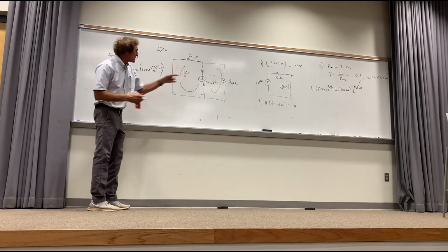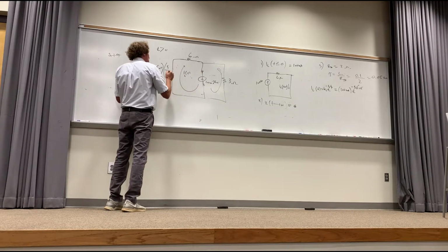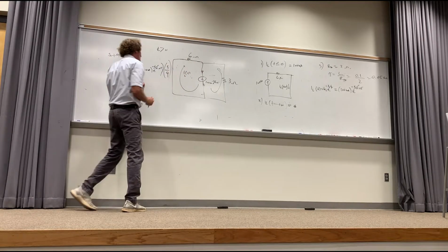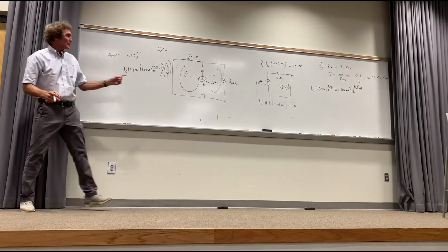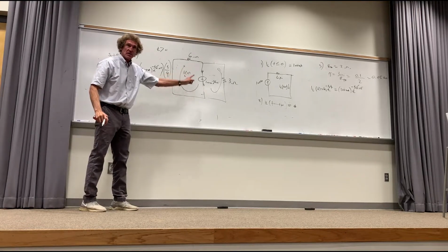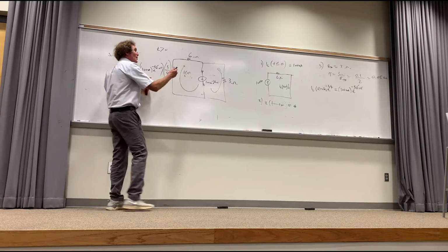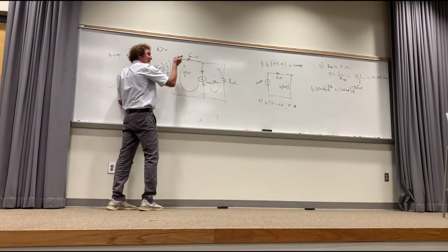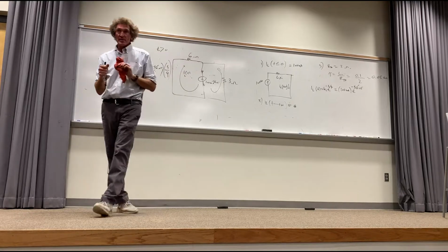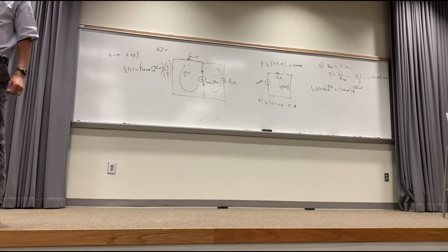So you take the opposite resistor, 3 over the sum of 3 plus 6, or 9, or 1/3 of that. Now that's going this way. You all see that, class? My current that I solved for is going down. Now, if they asked for the current going this way, it would be minus that. Can everybody see that?